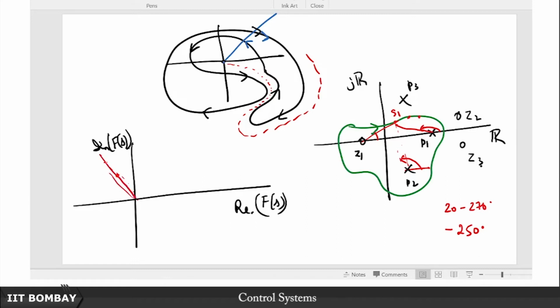So you see immediately you realize that it is kind of hopeless to try and draw this plot for a general case, right, how large this magnitude will be, and in fact we do not even care about the magnitude. After all, as I said, this entire Nyquist criterion is dependent on this principle of argument. So then what are we going to do about this, or how are we going to get an idea about how many times this plot is going to encircle, how are we going to convince ourselves how to interpret or read this off, because clearly even this 20 degree thing I just assumed arbitrarily. I have not been able to give conclusive evidence of what the configuration will be.